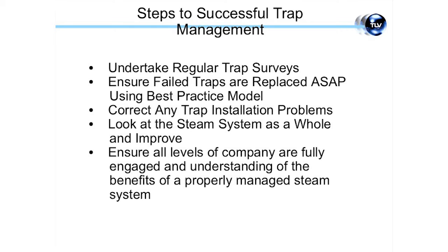The other thing is when you've identified the leaking traps and the block traps, something that a lot of people don't do, you need to replace them as soon as possible. It's no good testing it and taking a year to change the traps, which we do have customers who do that. You also need to correct the problem. It's no good just changing out like for like. Is it the right trap? Is the trap installation correct? Do we have the blow-off valve to get rid of the dirt before the trap? Are we collecting dirt in that trap rather than emptying the condensate? So we need to look at the steam system as a whole rather than isolated steam traps, and we need to do the improvement.